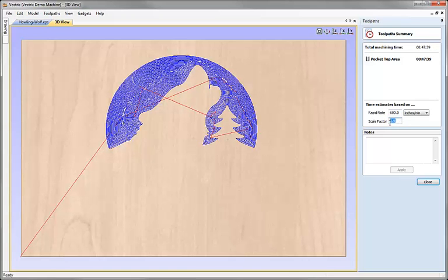In this case, I'm just going to leave the value at 2, and we're going to take this as being a roughly 32-minute toolpath, although as I say, that could vary a great deal depending on your particular setup. So in this case, we might be able to do this quicker by using a larger tool to hog out the majority of the area of this, and then the small tool just to make sure we're still getting the same level of detail around the profile.